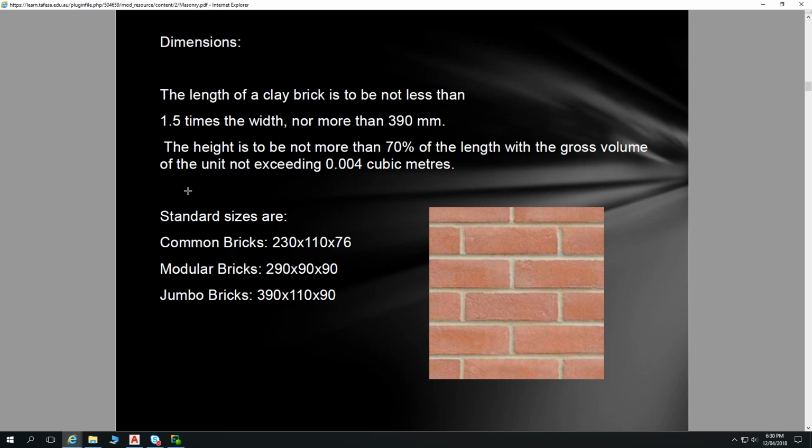Our bucket sizes on our excavators are 300mm, 450mm. So that dictates the size of our footing beams. The width of a bench is 600mm. The height of a standard bench is 900mm. So there's lots of